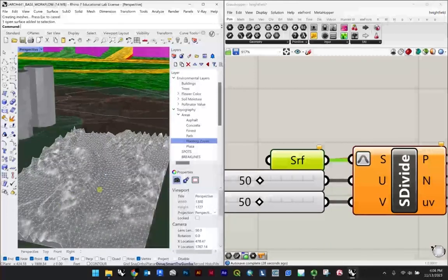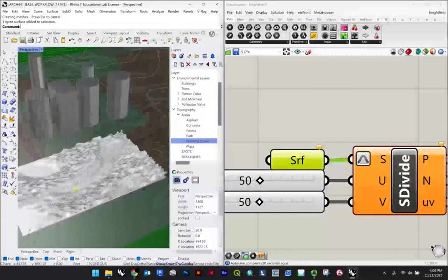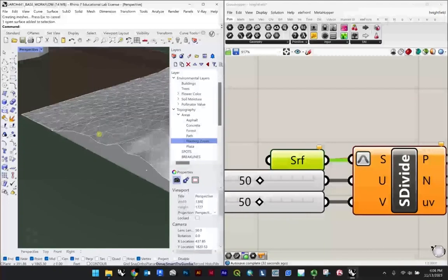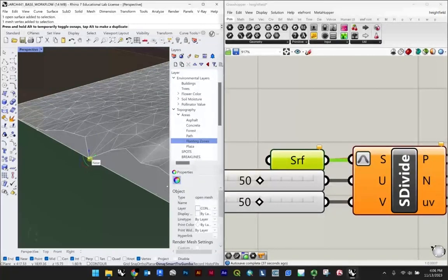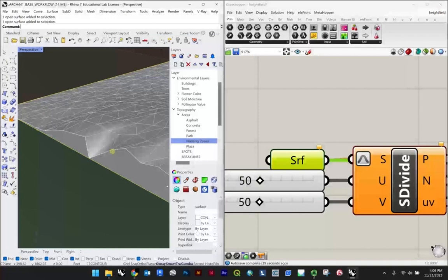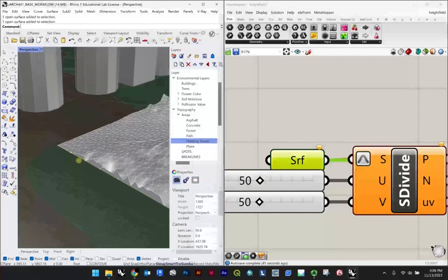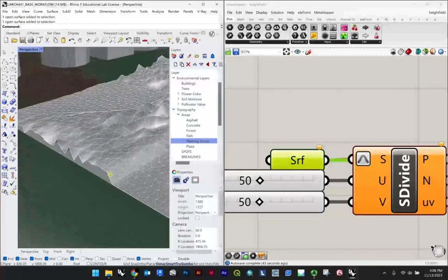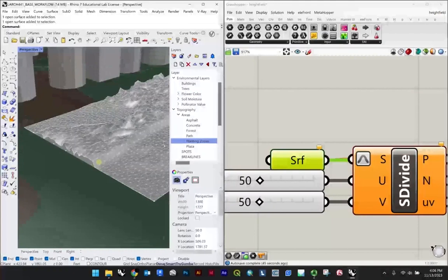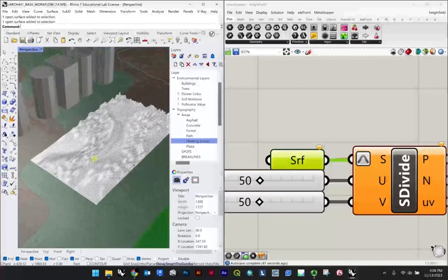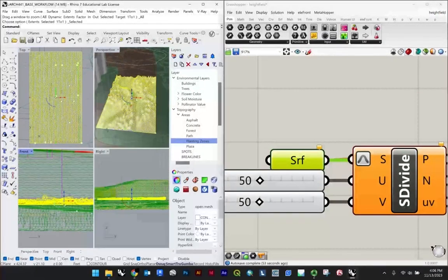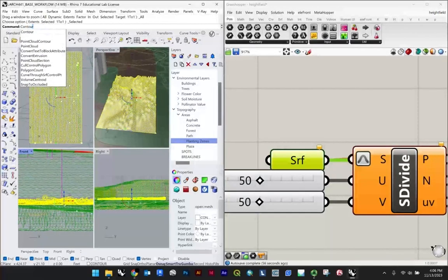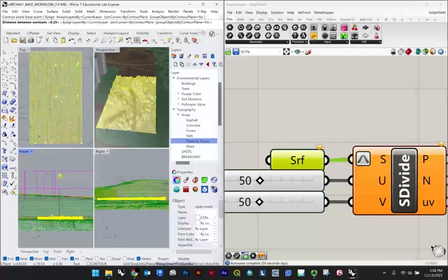Conceivably, depending on what you're doing, you could also start to drape this. Or in this case, if you have these edges, you can control shift and manually start to stitch this into your existing topography. There's not that many vertices you'd have to do, so it's a cool tool to get into site grading really quickly. And you could also go into this view and contour out some data. So let's just do a very fine grading, like 0.25 feet.